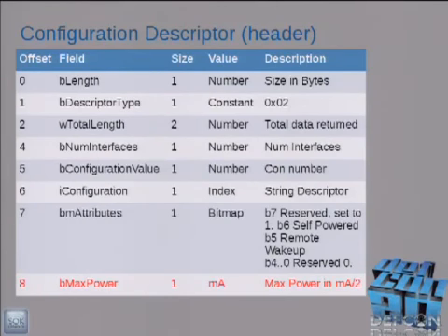Now, if you're going to make a little device, say something kind of like this, a little preview, that is going to fake another device, obviously I have some electronics that are going to require a little bit of power of their own, in addition to whatever my thumb drive takes. Some people might be tempted to just crank up that power. Don't do that. The problem is if you crank up the power and your port cannot provide that much power, it won't enumerate your device. So usually 100 milliamps is pretty safe, and it's probably enough anyway.